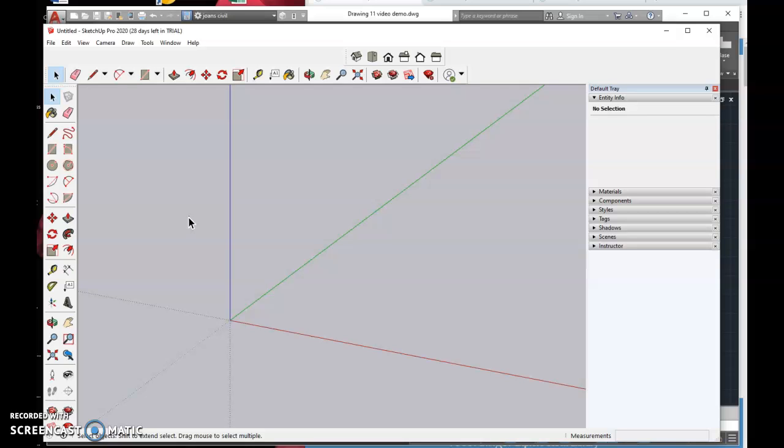I'm going to start with A, and I'm going to draw a box that represents the overall dimensions. I'm going to start with the front face and draw a rectangle. So I'm going to use this rectangle tool. I'm going to start it on the origin, and it wants to lay it down on the floor. So I'm going to use my left arrow key, and I'm going to force it up onto that face edge, right? That's the side that I would normally put the front view on,